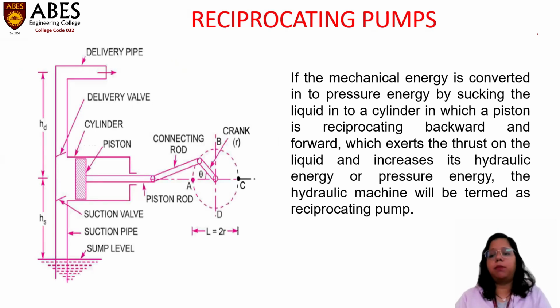Now the another pump we are going to study is reciprocating pump. If the mechanical energy is converted into pressure energy by sucking the liquid in a cylinder in which a piston is reciprocating backward and forward, which exerts the thrust on the liquid and increases its hydraulic energy or pressure energy, these type of hydraulic machines will be termed as reciprocating pump.